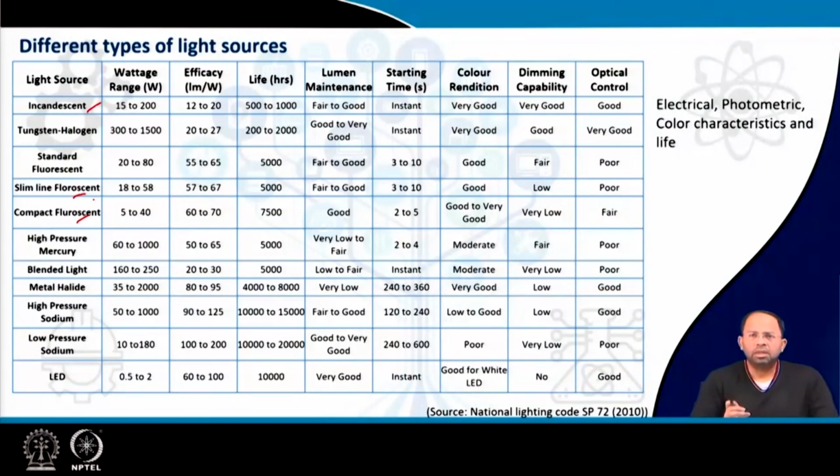In others, we want the quality of the light to be better, and so on. So you can see that when we select a particular light or a luminaire, that means the overall lighting fixture, the total unit, we consider electrical properties of the light, that is what kind of power it consumes, which you can measure in watts. Then we considered also the efficacy of the light, that means how much light is produced per unit of power, which is given by lumens per watt.